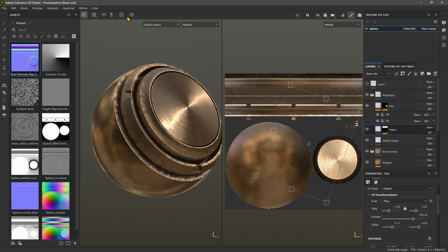Now these other two, you can see they are related to the manipulator. So this one here is the pivot point. Now the pivot point is the center grip. So if I click that, I can position that perhaps right here. So when I rotate, I'm gonna rotate around that pivot. When I scale, I'm gonna scale based on that pivot position. So it's kind of important.